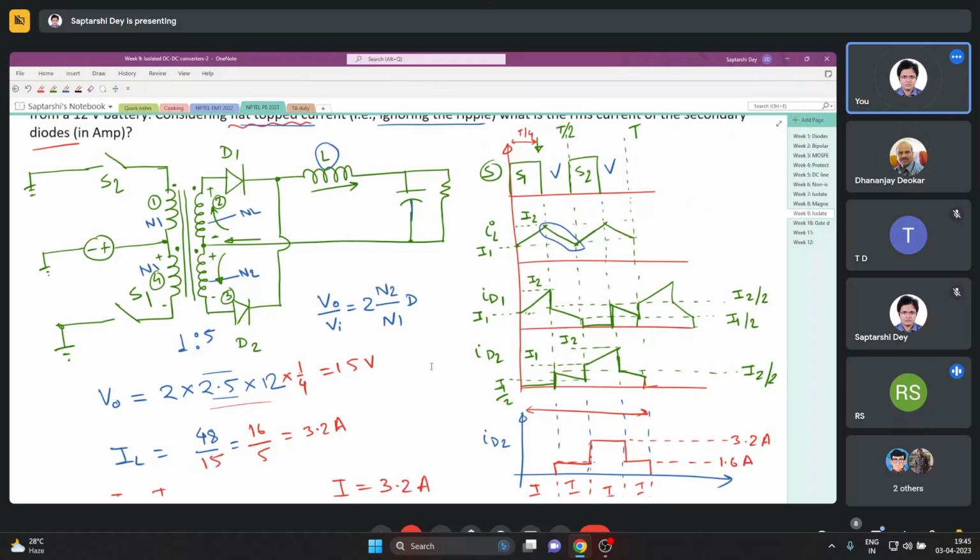Now for this case, say we are talking about an ideal transformer. There was anyway no flux flowing through it, and when the inductor current was reducing through the secondary windings 2 and 3, they are also not giving any net flux to the core, being equal and opposite. So the magnetics of the transformer is not disturbed by the inductor current of the secondary.